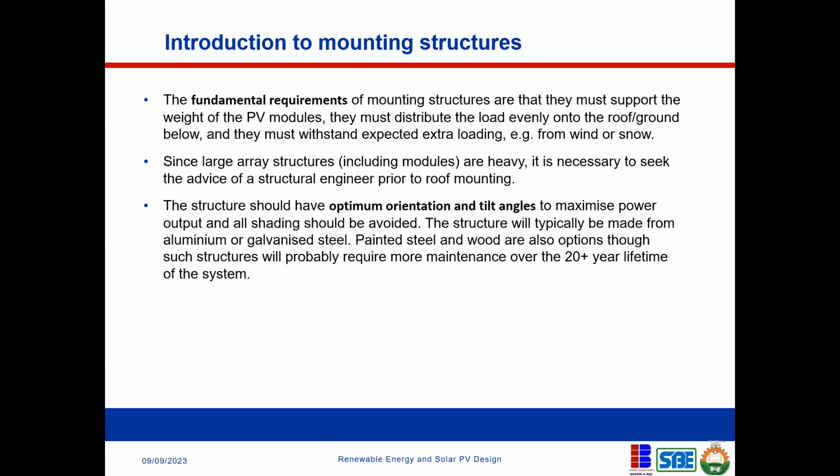So whatever structure you want to use to mount your PV panel, you should put heavy consideration on the lifespan of that PV module. So you don't go and use wood as your mounting structure, wood that will probably give way in the next 5 to 10 years, for a panel that is going to last for as much as 20 years plus. So it's important to make sure you use a proper mounting structure for it.